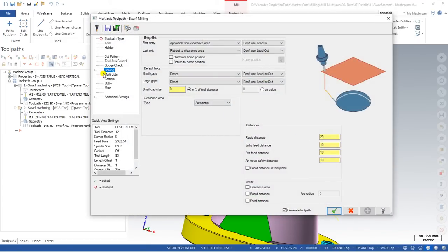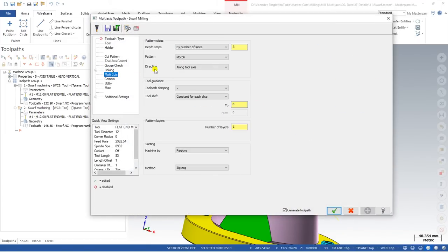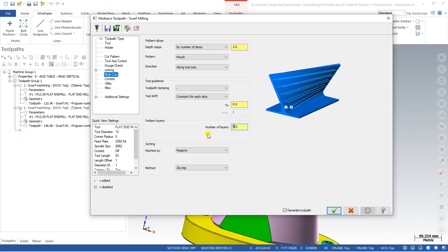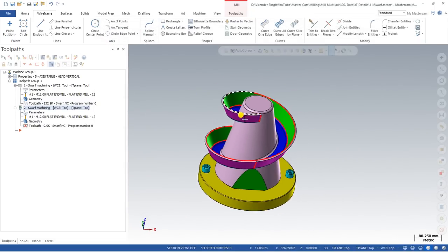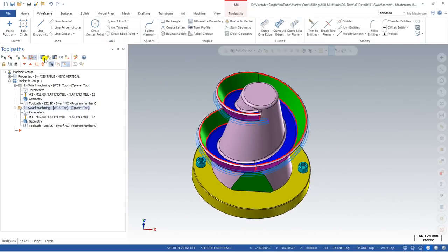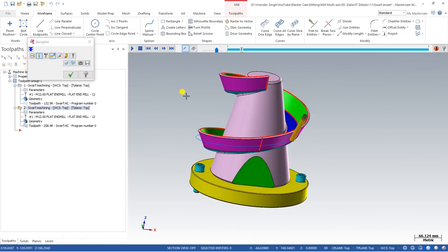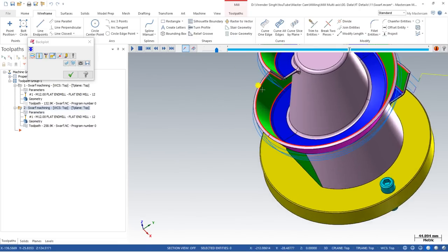Here, if we want multi-axis cuts, if my material is much higher or we want to make multiple passes, we can also define that my multiple passes should be 2, and you can define the step over value, which I make 5. So according to that, my tool path will run as the parameters we define. As you can see, my tool starts by cutting the outer portion first. It completes 3 passes, and now it comes to the inner area.